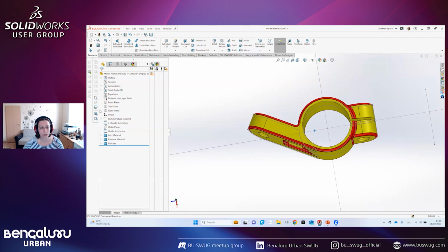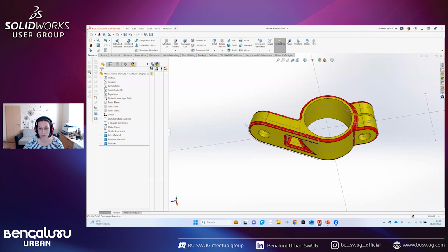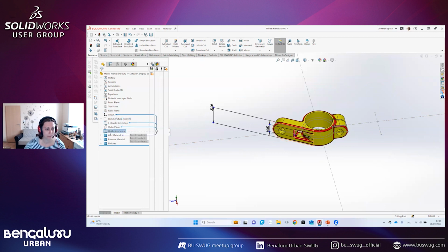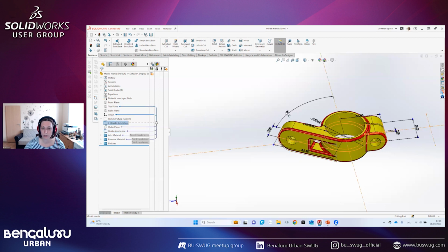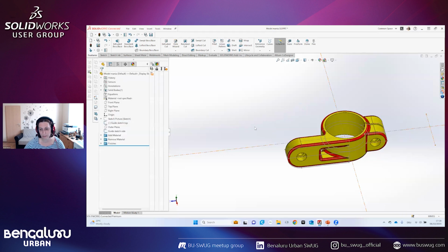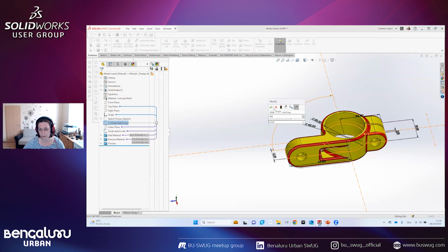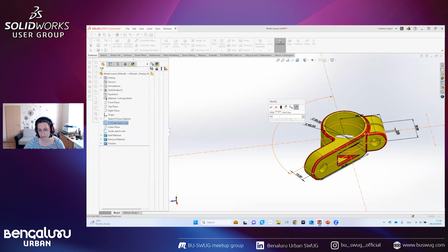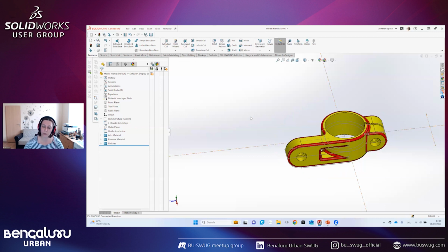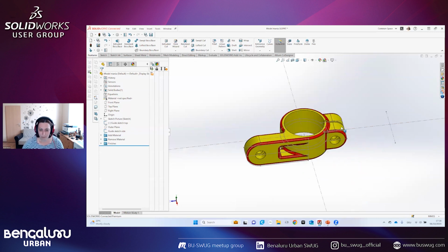If I make it just parallel to the, I don't know which one is this, to the right one, and coincident here to a point, then I will receive an error when I try to do that. Oops, let's go back to 90 degrees. And of course, I can move it also in the other direction if I want. Anywhere. And as you can see, everything is staying as it should be. This is what means a robust model, stable model, and one of the reasons to model with design intent.